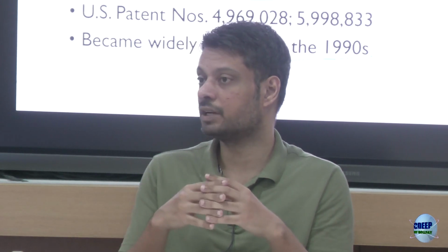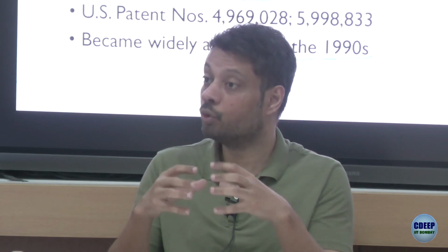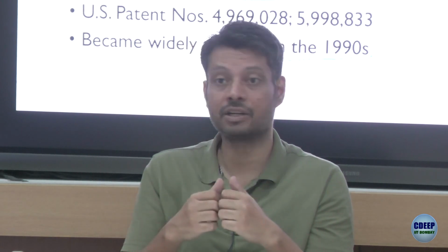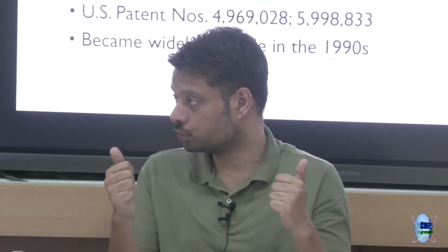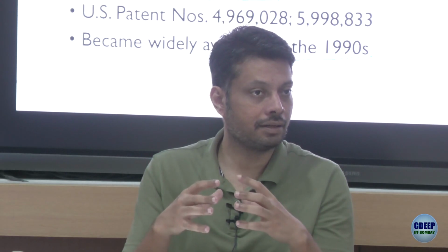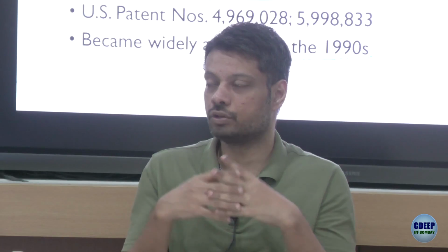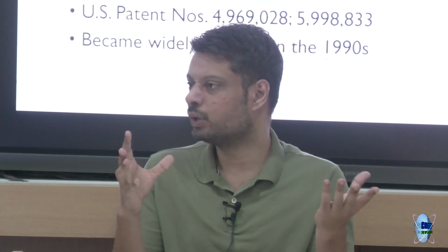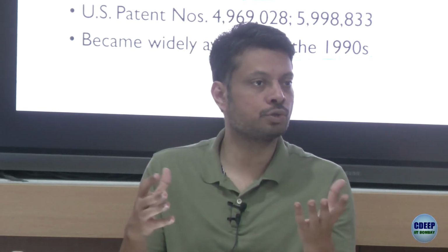So, if you say MOSFET was little power electronics, this could do higher power electronics, because it could block much higher voltage, and it could allow much higher current to flow through it. Imagine it as a more power-oriented device than the silicon MOSFET. If you are talking about mobile chargers, you have to handle some 325 volt, 400 volt, a few amperes of current, fine, one would use MOSFETs.